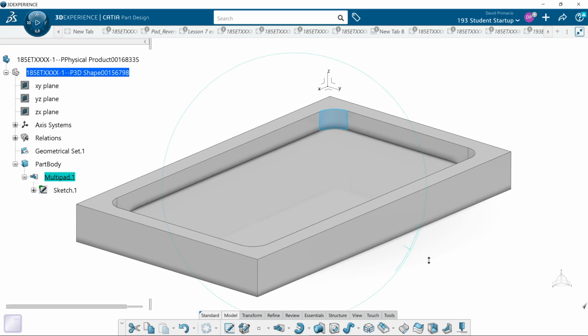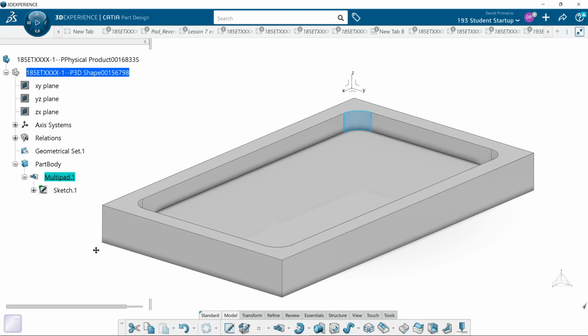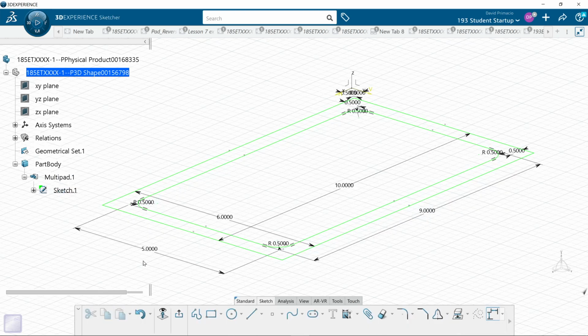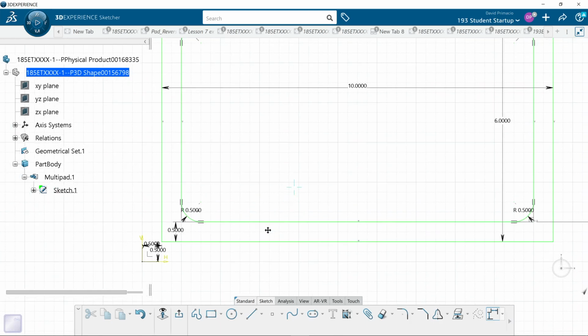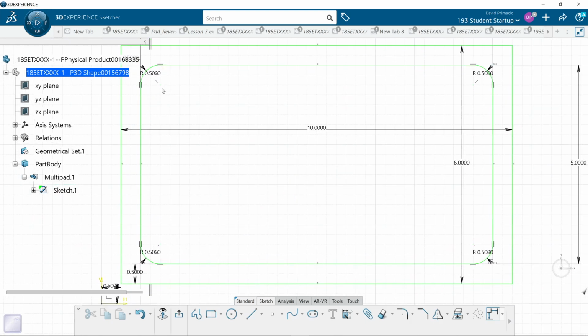What size cutter would I want to use to cut out this pocket? A 1-inch cutter. So if I were to put in a 1 inch cutter, you have a 1/2 inch radius, correct? In theory. So let's talk about this. This line and this curve and this curve and this line and all the way around, are all the curves and lines adjacent? Meaning, does this line and this curve touch at the same point, where they share the same point at each end of the radius going into the next line? Yeah, so they are adjacent.